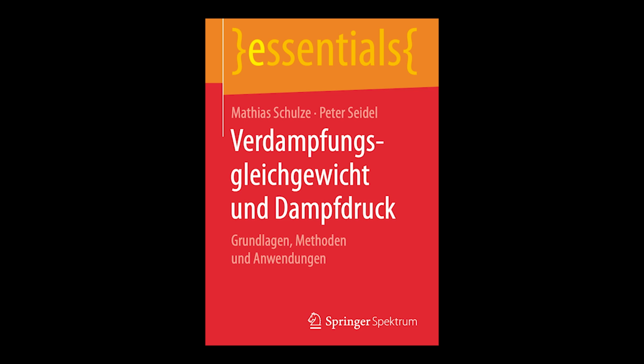Critically, as long as the liquid is present, the temperature is constant. All energy input just increases the vapor content. 3 is saturated steam. This is the endpoint of the phase transition, 100% vapor, but still at the boiling temperature. This is used for sterilization and things like that.